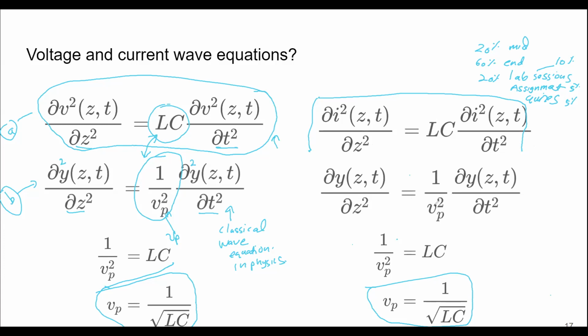Since the time is over, I will end the session for today. Today I was going through transmission lines. Transmission lines are basically used to transmit energy from one point to another. I explained the circuit model of a transmission line at a certain cross section with a length delta Z. We can denote that small cross section using inductors, capacitors, resistors, and parallel resistors.